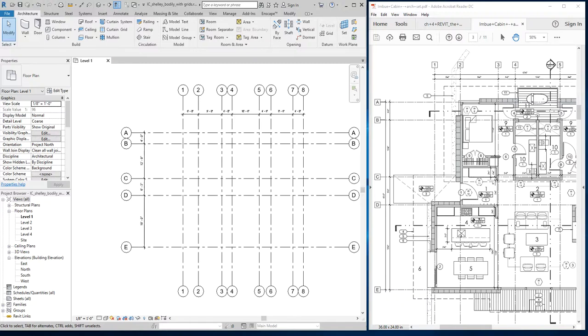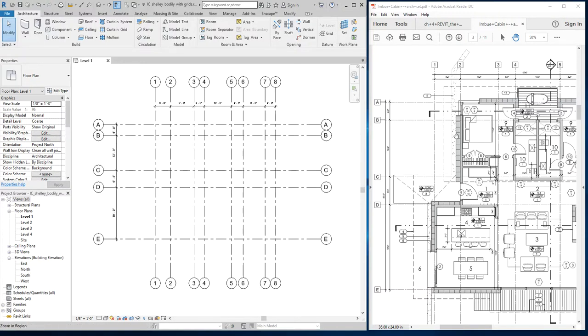All right, so we have kind of our system set up, and that will allow us to create our walls, right? So we know how to create walls, but how are those walls defined, right? That's going to be kind of the major topic today, is defining walls. And it's kind of an important topic because the process we're going to follow to define walls will be the same process that we follow to create floor systems and roof systems and new components, or we call them families in Revit, but blocks. And to create any, quote, new type of item, we're going to follow the exact same process that we're going to learn today to create brand new walls, okay?